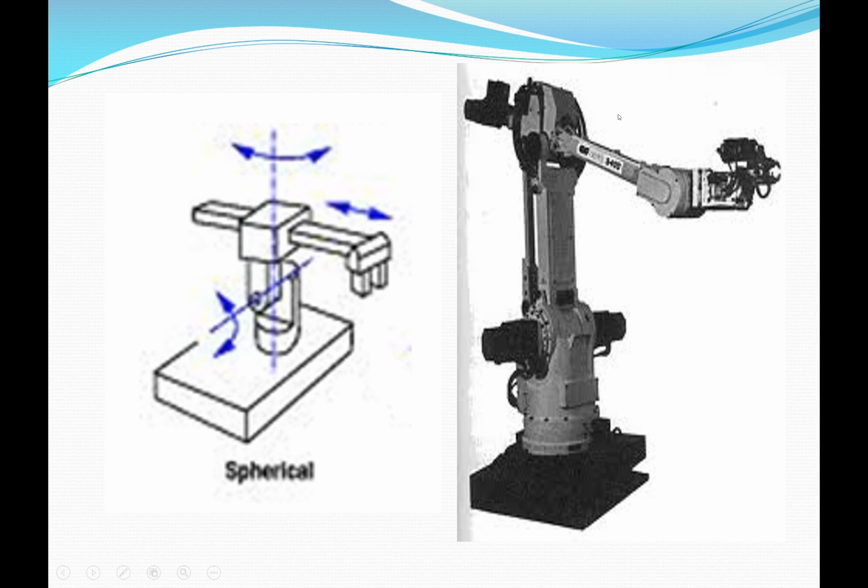So again, you have to identify where the joints are. There's one joint here that's rotational. This joint here is definitely rotational. This joint here is rotational. Now, if there is a joint here, which it looks like there is because there's a motor here. This motor right here is driving a worm gear that extends this in and out. That would be a prismatic joint right there. And then there's also a joint here that rotates. And actually, there's probably something out here, but it doesn't really show you. I'm going to treat this whole thing as the end effector right there.